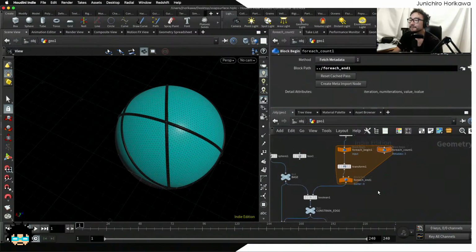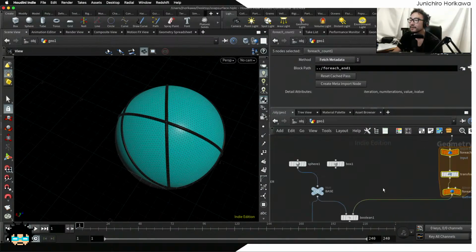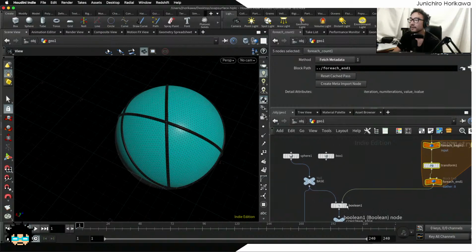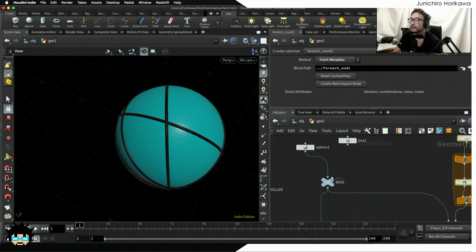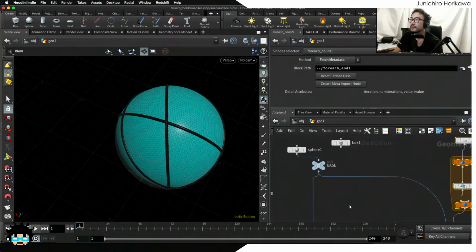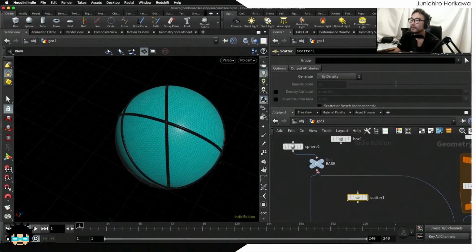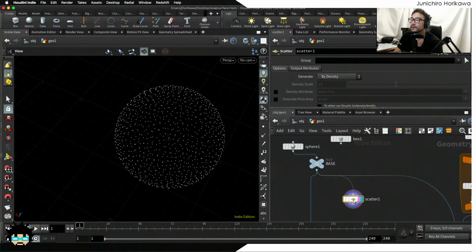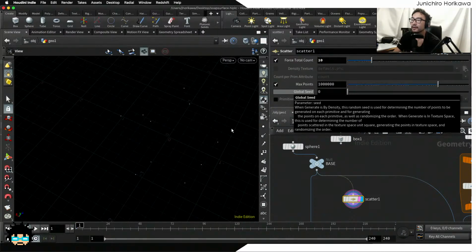Right, so let's also try to make a Voronoi-like shape constraints curve, which is pretty simple to create. I'm gonna use this base, and then to create a Voronoi, you need a scatter point on top of the surface. Maybe this is too much. Reduce this to like 10.